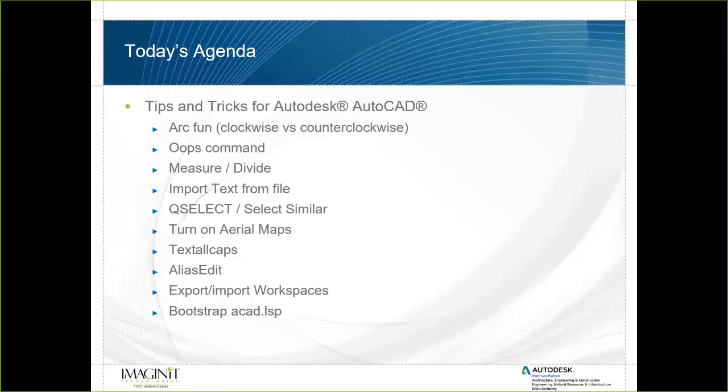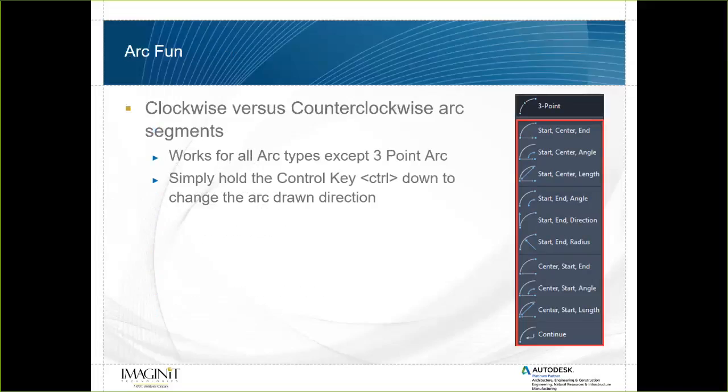So the first thing we're going to do is start with some arcs. Normally when you draw an arc, it's going to draw the arc in a counterclockwise direction. And what you do is you simply hold down the control key and it changes the arc direction. This is a very easy piece to understand.